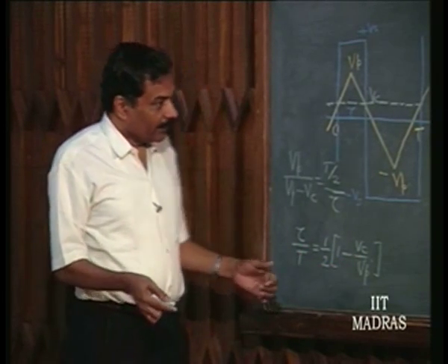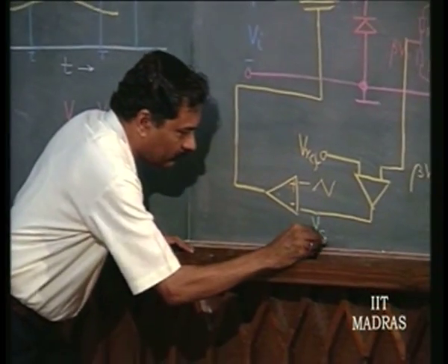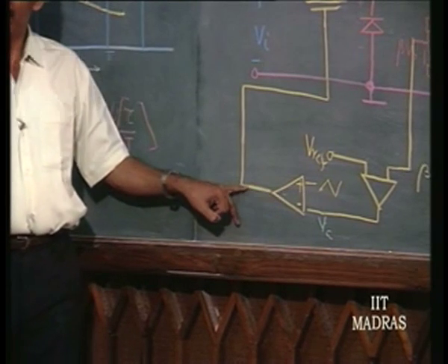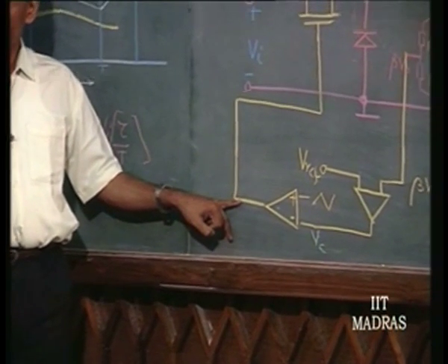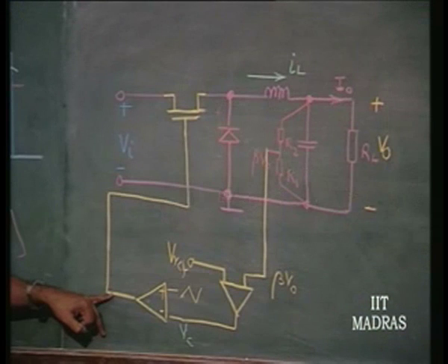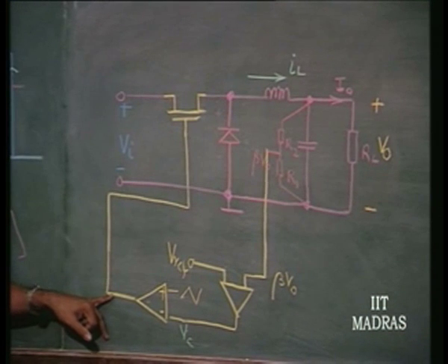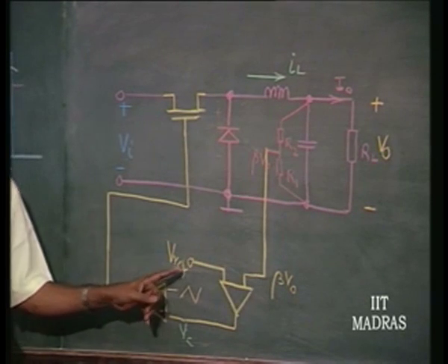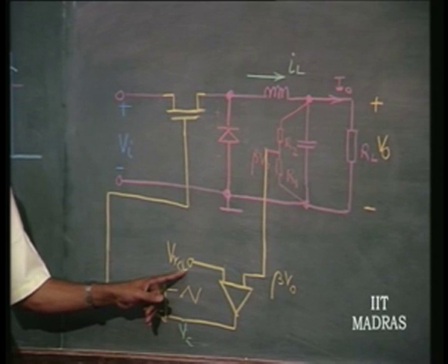So, the control voltage we see here is going to modulate this train of pulses occurring at a frequency equal to 1 over T in a suitable manner, so that this voltage is the same as this voltage, right.